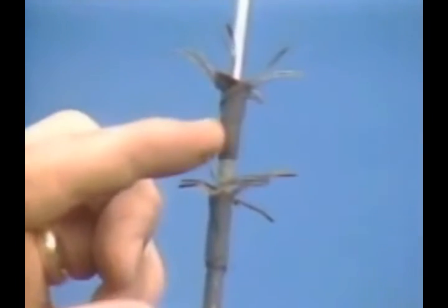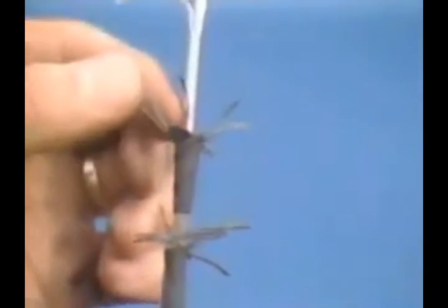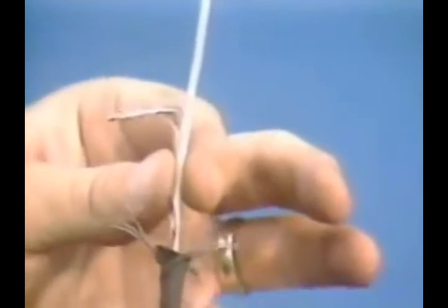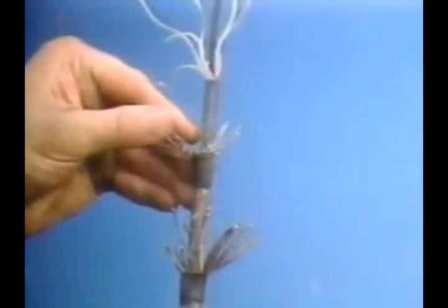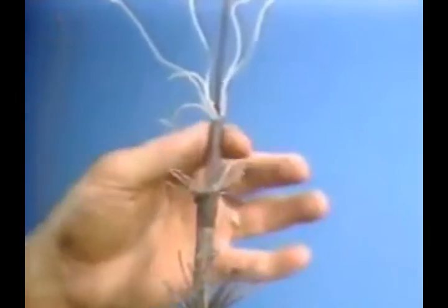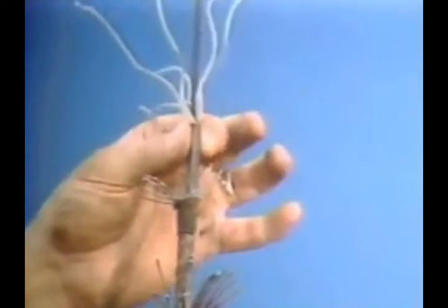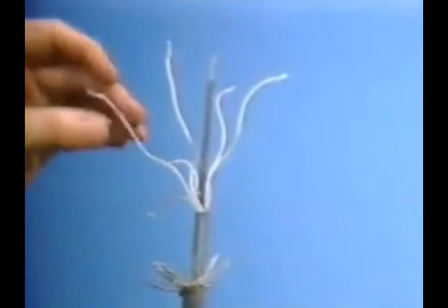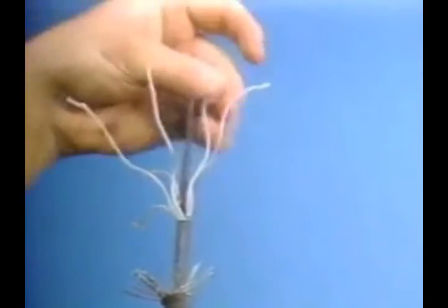The monoconductor cable normally used for perforating is an armored line with several layers of armor and with an insulated conductor core. If multi-conductor cable is used, as is sometimes the case in low-pressure situations, the normal 7-conductor electrical wireline cable is used, with its armor layers and individually insulated conductors.